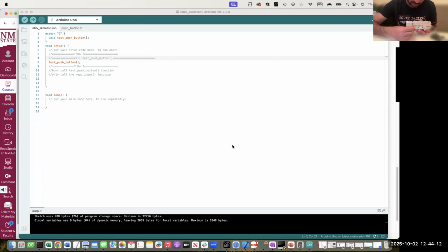So if you see the push button, now this brown cable is connected with pin 9 on the Arduino board, which is basically pin at index 1 of port B, right? And I just removed it, just to demonstrate what I want to do in this task. On the other side of the push button, I have this orange colored jumper cable which connects one leg of the push button with the ground, right?